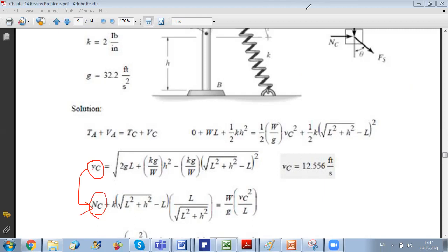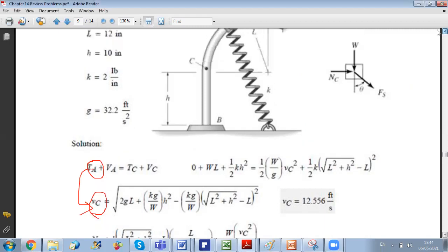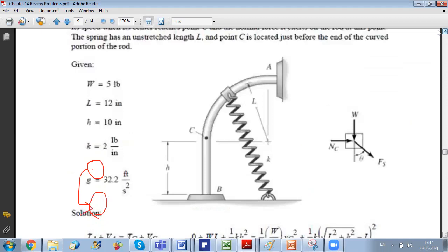the normal at C does not have to be towards the left, right? The normal at C, okay, how do we know? Look here, you can make an assumption. It could be to the left, it could be to the right. You know why? Because it depends on the value of Fs. You can assume it towards the right and calculate. If you get a positive value, it means it is to the right, and if you get a negative value, it means it is to the left. But both scenarios are possible.